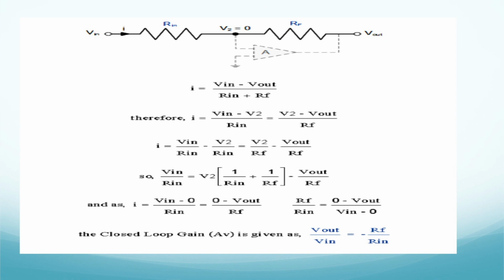Now if you just see, Vout is equal to minus of RF by Rin into Vin. Suppose you give a value of RF to be 1 kilo ohm or 1 ohm and Rin to be 1 ohm, you can see that Vout will be equal to minus of Vin. Now what it says is that whatever input you provide at the negative terminal, the output of your operational amplifier will be of a negative value. A positive input you provide gives a negative value in the inverting amplifier circuit.